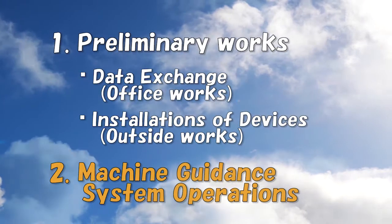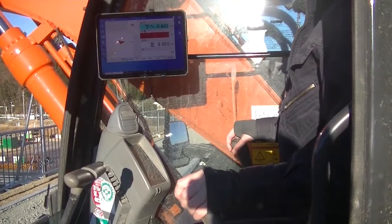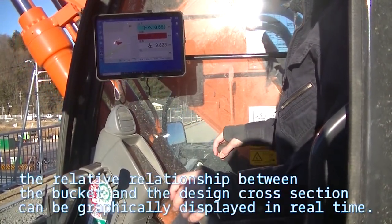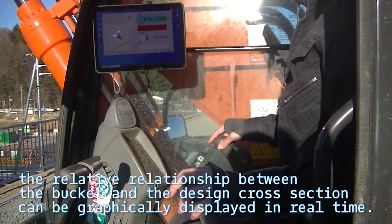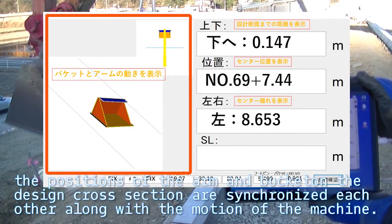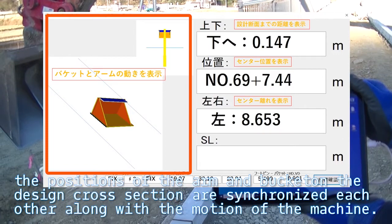Now let's try out operating the machine guidance system. With this machine guidance system, on a monitor installed in the cab, the relative relationship between the bucket and the design cross-section can be graphically displayed in real time. On the left side of the monitor screen, the positions of the arm and bucket on the design cross-section are synchronized with the motion of the machine.